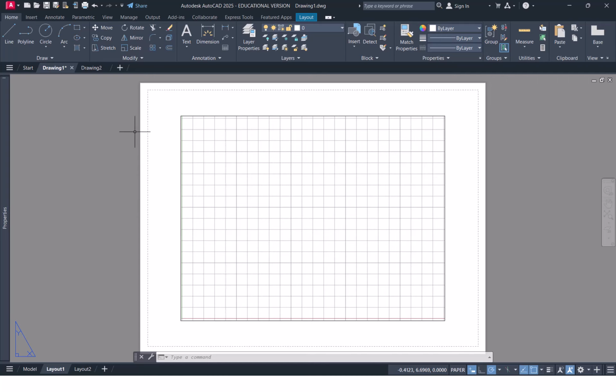But in this class, in 1101, we'll do all dimensioning and all text in paper space unless the assignment tells you differently, because there are a couple of assignments in this class in 1103 where we will do model space dimensioning. All right, so the paper space, the layout here, we've got a piece of paper.